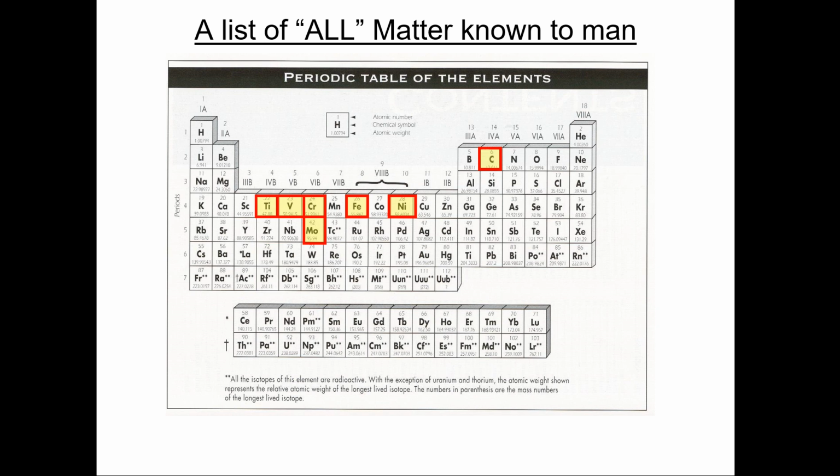And titanium is commonly found in tool steels and in stainlesses because titanium loves to mop up impurities. And it does this very well. Silicates and titanium do a lot for us, especially when it comes to stainless. Phosphorus, we already talked about that. Silicon. Let's talk for a moment about this W here, which happens to be tungsten itself.